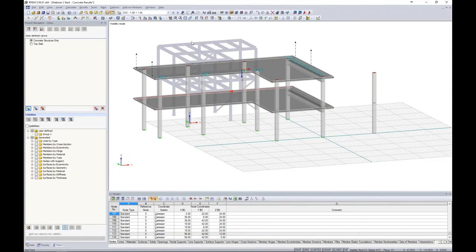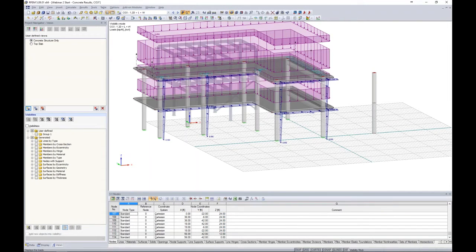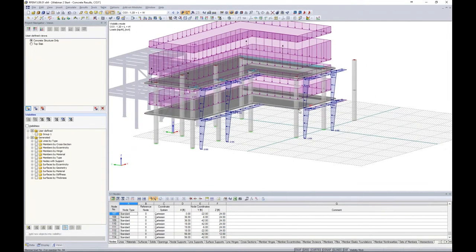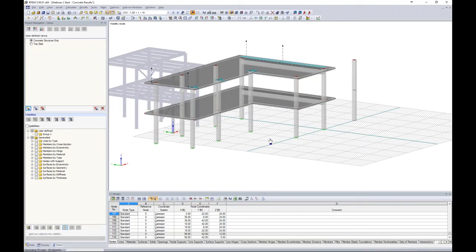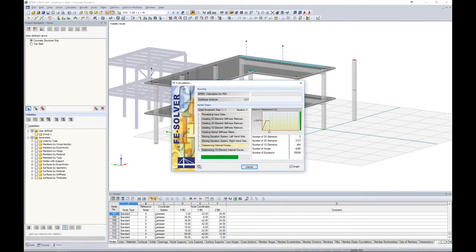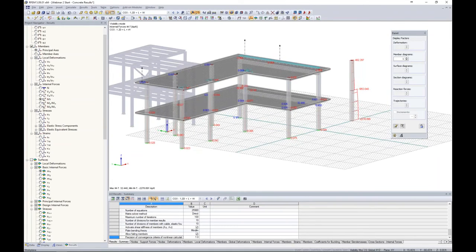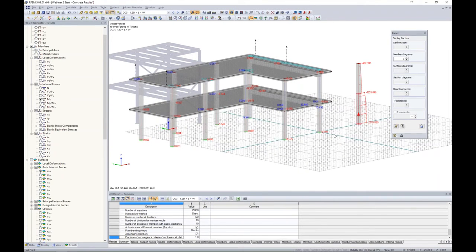Now I'm going to run one of our load combinations where I have a lateral load applied. So you can remember from webinar 1, we applied a wind load in the Y direction here with some gravity loads. So if I run this first load combination, then you will notice that after the result is complete, I have my member over here with some results as well. So what's exactly happening? Well, I want to view my results on my members like I would any other member within the model.